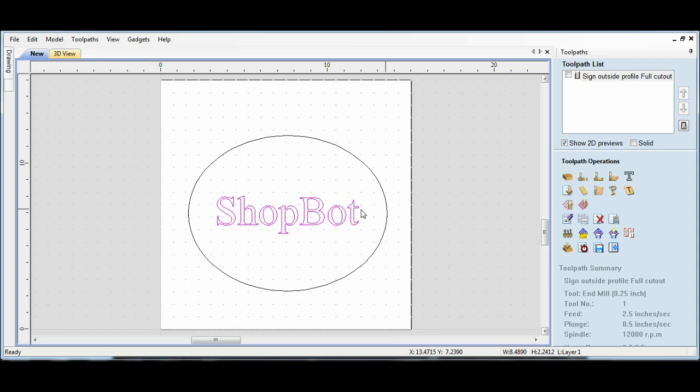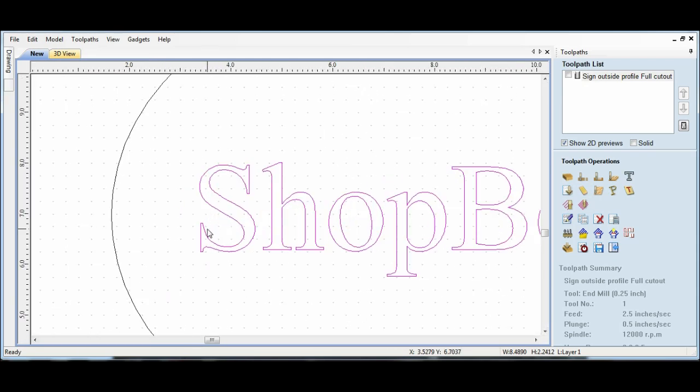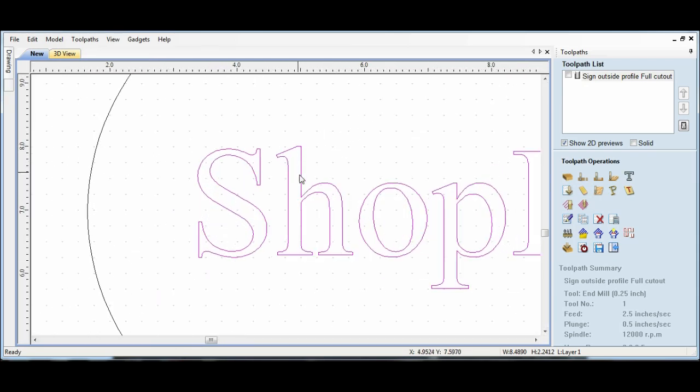And if we zoom in on this lettering, as you can see, the letters are thinner and then wider. The O here is nice and wide here, but thin up here. The V-carve toolpath is perfect for this, because it's going to set its own imaginary center point on the center of these two lines. On the center of the outside two lines is what I mean.